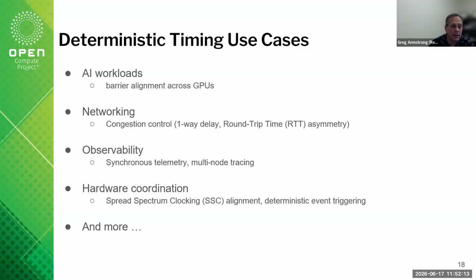Even the PCIe SIG forum for the PCIe clocks is talking about, instead of maybe always having to rely on common clock, and where even independent clocking, where the spread could be happening independent from each other, you could use this to actually get coordinated spread spectrum clocking within this. So this will help with deterministic behavior. You still get the benefit of the spread spectrum for EMI considerations and stuff like that.